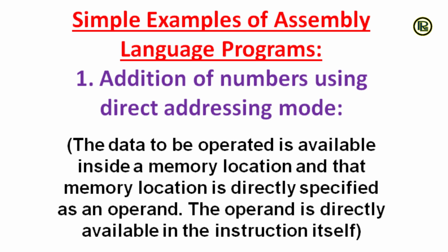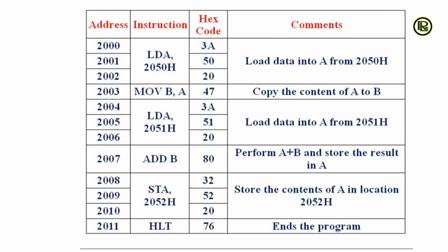And what is direct addressing? The direct addressing mode contains the concerned operand in the instruction code's address field. It requires no memory references for accessing the data. So it's a very simple and fast process. It takes less time to execute the program and getting the result is faster. So I have the example here.